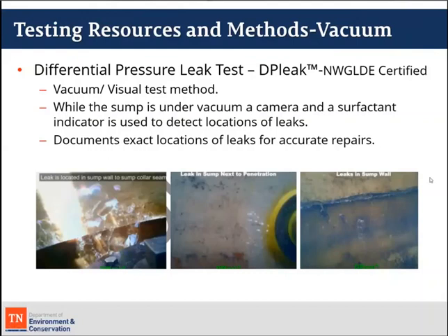But whenever you're performing your hydrostatic test, it's kind of the opposite. You want to close that pathway off. It's important that you close those entry points off because you could have your water migrating into your piping run that could indicate a fail of that sump.